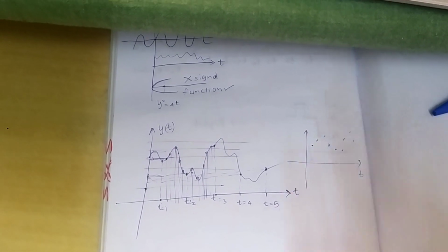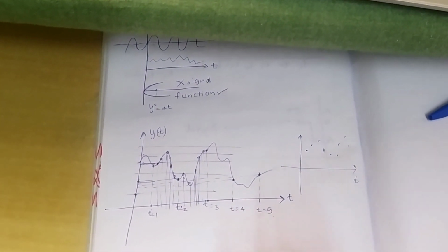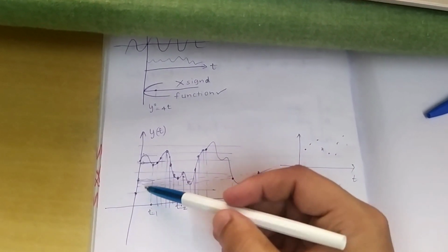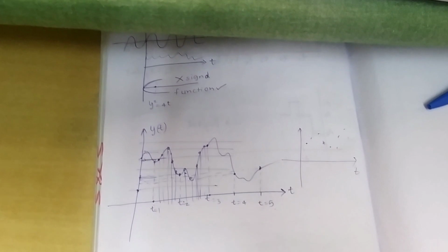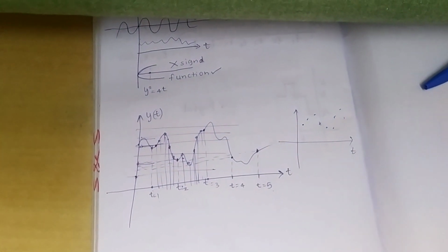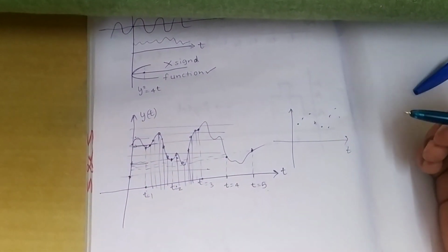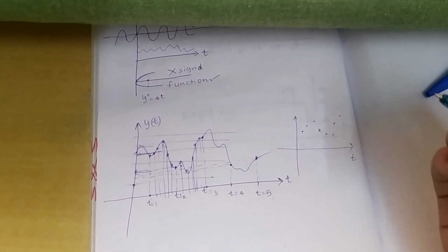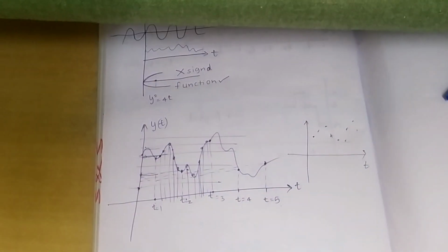That sums up how an analog signal is converted into a digital signal. First it is discretized, then it is segregated according to different values of voltage or amplitude. Voltage is when you have an electrical voltage signal, so I meant it like that. When you quantize it according to the value of amplitude, you convert an analog signal into a digital signal.